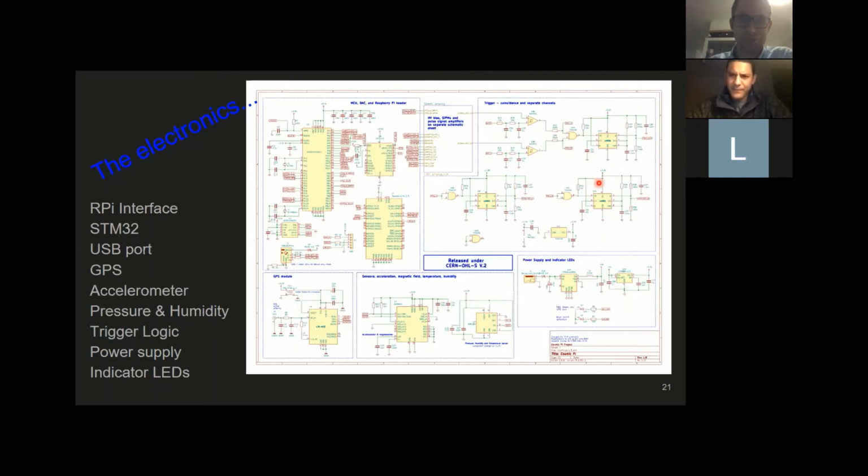Those of you who are electronics geeks will know that the 555 is one of the oldest and most well-known semiconductor chips there is. And we use this to stretch out the pulse. So the signal that we get out of our AND gate is literally a few nanoseconds long, but with a 555 timer, we stretch it to make sure that it is at least 2 clocks of our microcontroller in length. This means that when we send it as an interrupt, we can detect it reliably. Anything less than that, there is a risk that the microcontroller will miss it as an interrupt, and that would be a cosmic ray, which we didn't capture.